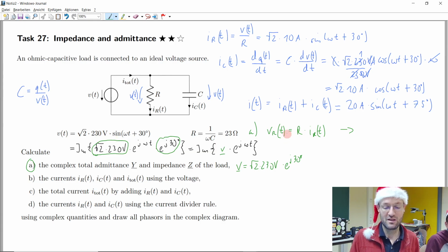Okay, and so now we could take this equation and insert it here. Take the very same equation for the current and insert it here. And then do some manipulation. And at the end, we would find out, okay, this equation, if we insert this stuff into this equation, long story short, the complex voltage phasor is the same as the resistance times the complex current phasor. So Ohm's law for DC currents, for time functions, for complex phasors looks exactly the same.